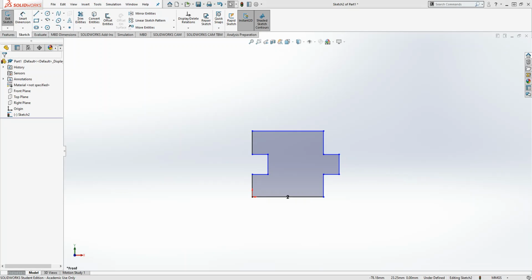With these lines that I have here, I never smart dimensioned them, but if I wanted to, I could easily. Say this whole segment from the bottom line endpoint to the top endpoint was 2 inches. I could translate my whole entire part that I'm doing a linear sketch pattern on up 2 inches, so that both endpoints end up connecting on the exact same point. So this is a very useful way to create these extending patterns and save yourself a lot of time if you're creating something that requires a lot of pattern work.